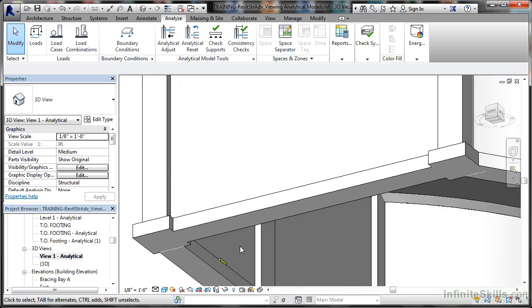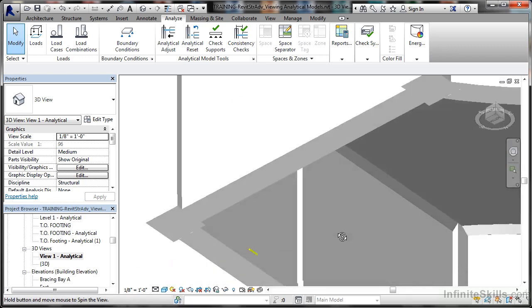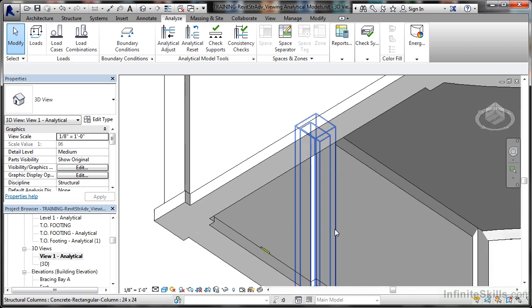And then I release like that. And you can just see the loadings. Can you see them? Inside the building themselves. Now again, you've got to be careful how you move all of this around. So you want to be able to see everything like that. Now, don't forget, you can select these walls and these footings and things and actually hide those and isolate them, remember? So that's what we need to do now.